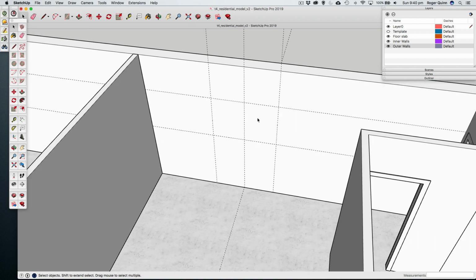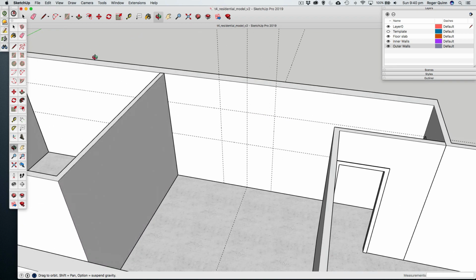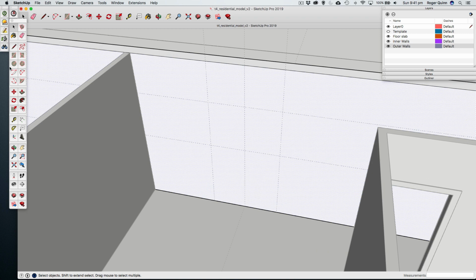Now, most importantly, just checking whether this wall is grouped or not grouped, and I believe it's grouped. It is, so I have to double click that so I can get into the edit mode. I can tell I'm in the edit mode because I can now select individual surfaces. Tremendous. And so now I can successfully draw a new rectangle on that space, which will edit that geometry.